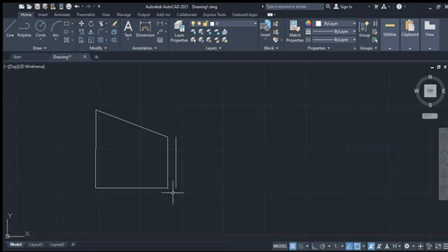Now I can now mirror. This is the tool for mirror. You select the tool and you select the object like that. Now you can now pick this edge. You want to mirror here, so by 100 we pick this edge and move it this way. Can you see it now? If you don't want it to be inclined, you can just come here and select orthogonal, so it will be just easy like this. You can see now, and enter. I've been able to mirror this object to this side.